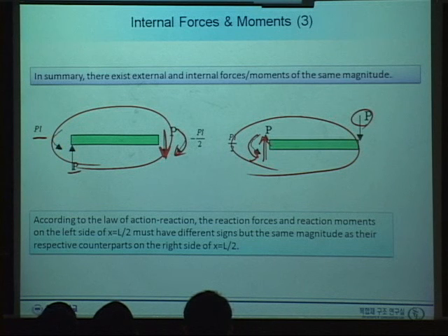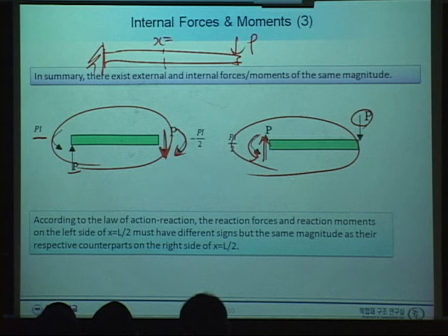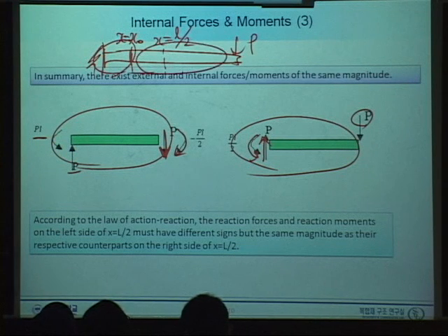Well, this is a beam with P, and at the section x equal to L/2. How about in another position, x equal to some other arbitrary position? You can calculate in exactly the same way you did. And again, you can calculate this internal force at this section either from the equilibrium of this part or the equilibrium of this part. Okay, the answer should be the same.